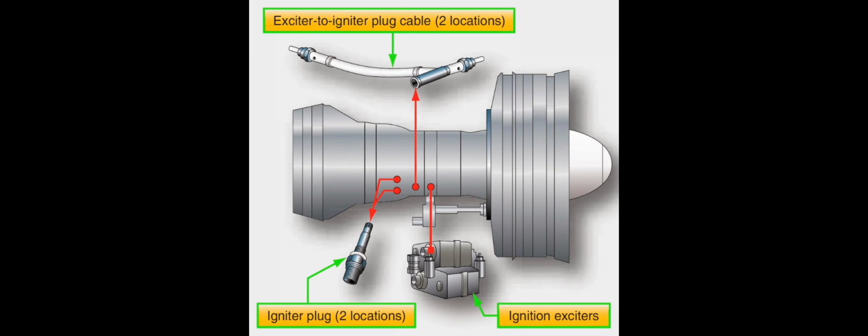When are turbine engine ignition systems normally in use? Only when starting or restarting. What are the two types of igniter plugs? Annular gap, constrained gap. What is an advantage of air turbine starters when compared to electric starters for large turbine engines? Lightweight, faster cool down.